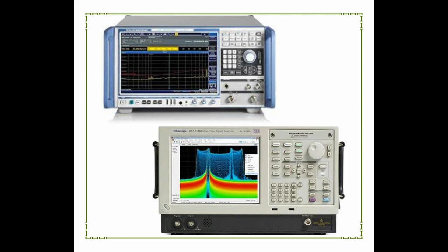Spectrum analyzer manufacturers should list, as a minimum, performance specifications such as frequency range, frequency span, residual FM, resolution bandwidth, input impedance, dynamic range, spurious response, sensitivity, shape factor, noise sidebands, display mode, for example linear, log, square law, and so on.